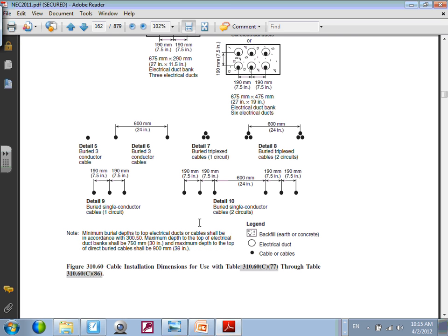No, I mean, you just said low voltage is 600 or less. Yeah. Medium voltage. What happened between 2000 and 5000? What happened between 2000 and over? There is no system that I know of that's between these two voltages, unless it's a special system. The NEC calls it over 600 volt. It doesn't matter. They don't use the term high voltage. Utilities use medium voltage and high voltage.